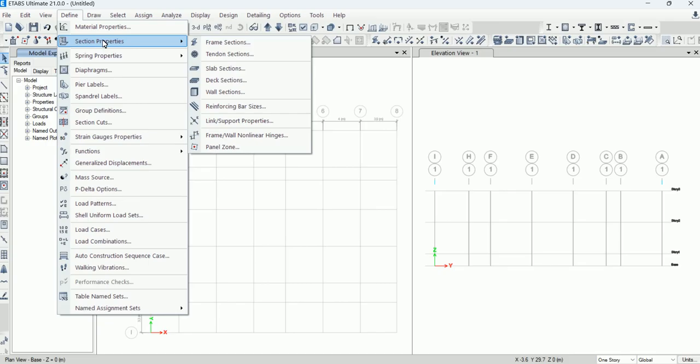We only provide slabs to apply our loads, floor loads and dead loads, because the slab has a significant dead load itself. We can export that slab to SAFE for design, or we can use our stress and steel area by putting them in Excel sheets. Slab design is very difficult, because we have sheets and coefficient methods, many methods, even finite element methods, and coefficient methods.